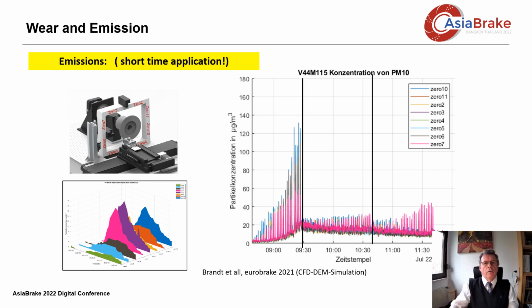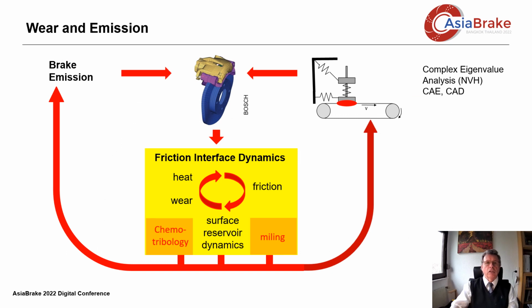Measurements on the described tripod tester allow very detailed statements about the flow dynamics of brake particles and equally precise analysis of the influencing parameters. We have shown this with complex CFD DEM simulations in 2021. My vision is that not only friction itself, but also wear and emission can be described by a differential balance equation, as I've shown at the beginning of this talk.